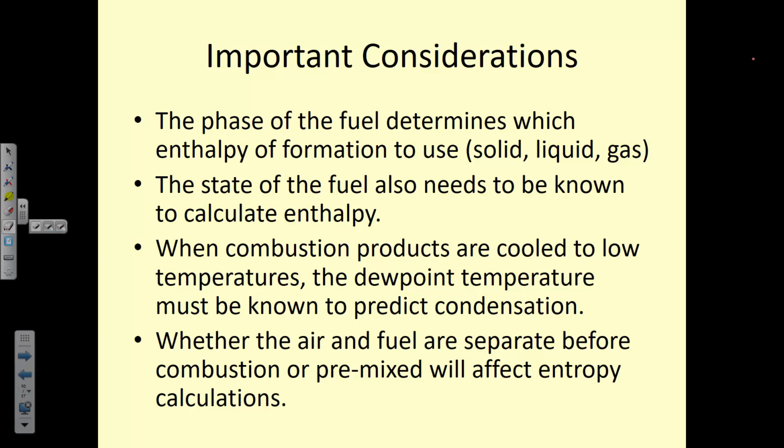You also need to know the state of the fuel so that you can calculate the enthalpy of the fuel. So enthalpy of formation, in addition to that, you need to know so that you can know whether the ideal gas assumption is valid and if you can just use ideal gas tables or if you have to use a correction factor. Maybe you use the ideal gas table to get the initial value, but then you have to use those compressibility tables to find the actual value. So you can see how these problems could get even more complicated as we could add additional layers to it.